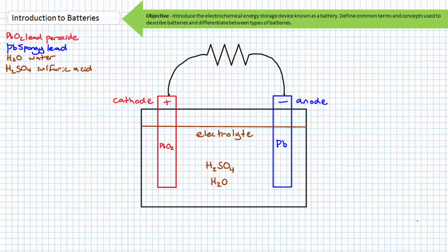If your goal is an understanding of the electrical aspects of a battery, the nitty-gritty chemical details can be summarized as such. At its most basic level, a charged battery is one in which there is a chemical imbalance. A charged lead-acid battery has a lead peroxide cathode and a spongy lead anode. There is a chemical difference between the cathode and anode. These electrodes are immersed in an electrolyte. In the case of a flooded lead-acid battery, a mixture of sulfuric acid and water with a given concentration. The aqueous solution of sulfuric acid and water disassociates some of the hydrogen ions from the sulfuric acid molecule, forming positively charged hydrogen cations and negatively charged HSO4 anions.